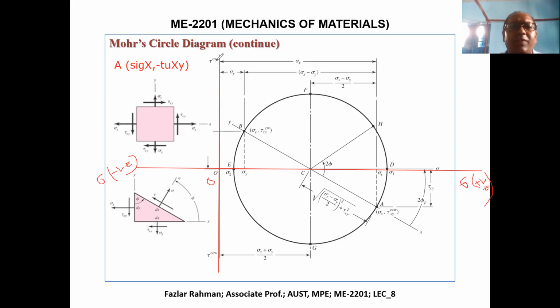Over here it is showing tau clockwise positive. So upward is obviously positive. Now which one is positive, clockwise or anti-clockwise? In the Mohr circle, we know clockwise is positive. Normally I put it this way. If tau is clockwise, I'll go upward. And this one is negative tau, if tau rotates anti-clockwise. So this is my x-axis, y-axis, I fix it.